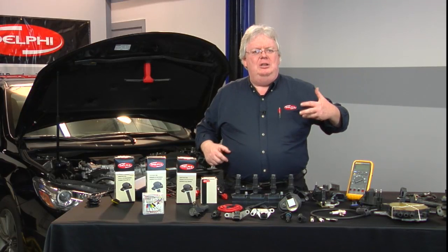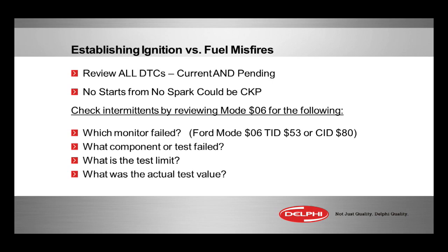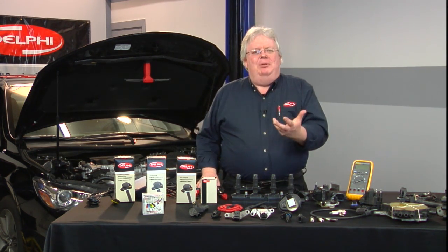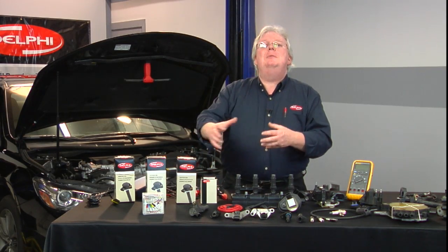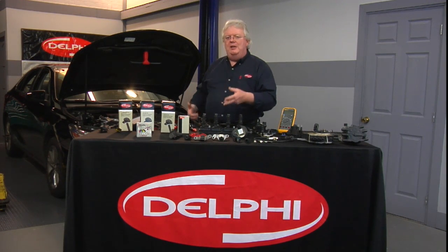When you have an ignition misfire suspicion, always good, no matter what you think's wrong with that car, to run all DTCs, check every module. Remember, it's not just a powertrain or engine management system. It's a complete vehicle where a lot of things are overlapping and working together in concert. So run all modules, all DTCs, and especially in the PCM, look for those pending codes to get the big picture. Remember, you could have an ignition module that's not the problem. The ignition coil can make spark, but it could be some diagnostic circuit that makes the computer think it's not working correctly and shut the injector down. You have a misfire, but it's not really a misfire. So more on that later.